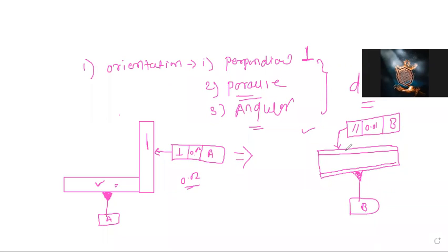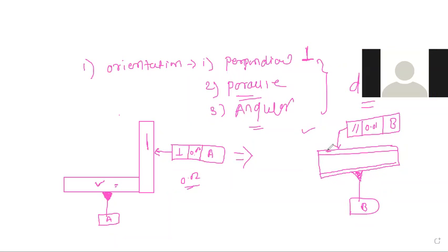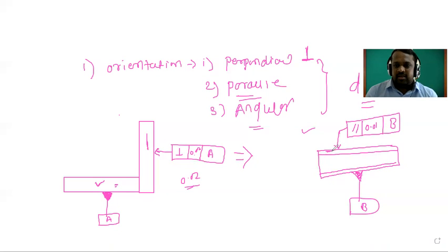First surface parallel to second surface within tolerance 0.01. This surface should have parallelism with tolerance zone 0.01 mm to the datum plane B. Good, it is good. This is the parallelism of this surface within 0.01 mm tolerance with respect to datum B. Taking this as the reference point, how parallel it needs to be within this tolerance. If it is within it, we can say it is acceptable. Okay, understood.